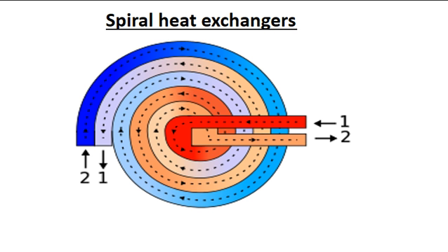More generally, the term refers to a pair of flat surfaces that are coiled to form the two channels in a counterflow arrangement. Each of the two channels has one long curved path. A pair of fluid ports are connected tangentially to the outer arms of the spiral, and axial ports are common but optional.